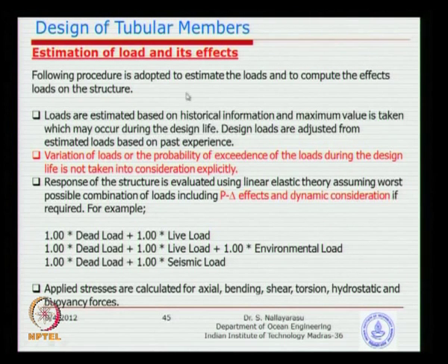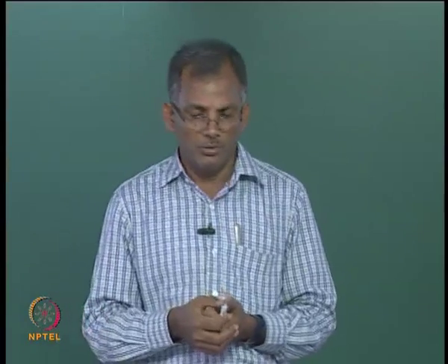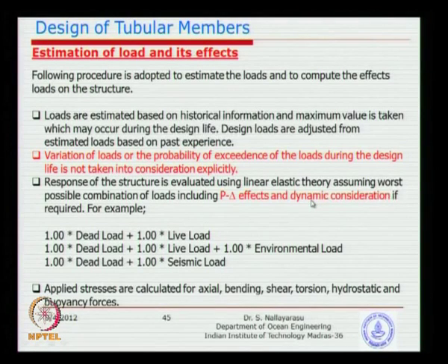So, basically that gives you an understanding of how the allowable stress method is working. Of course, if you require, additional effects due to P delta deformations could also be included. Nobody is going to argue that allowable stress design cannot have nonlinear stress distribution, or cannot implement the P delta effect or the dynamic effect, like for example in offshore structures where we have dynamic loading, which always causes trouble. So, you could include all that; the only problem is how we implement it, which is a major issue.